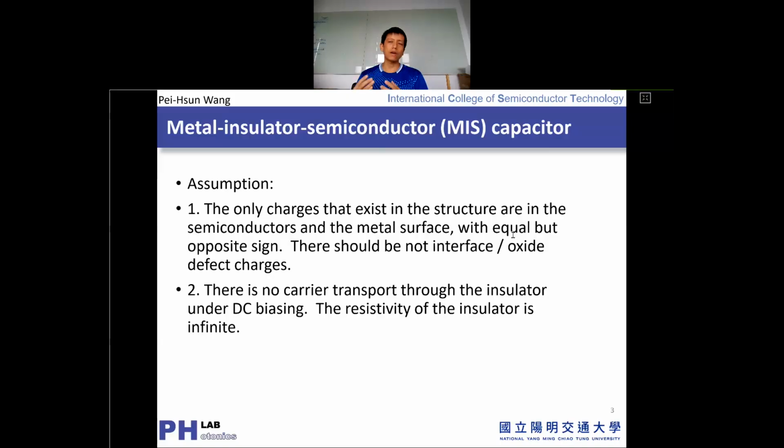So this is easy to identify. We can just have a silicon wafer, and then we do the oxidation. And then we connect both layers with metal connections, either the ohmic contact or the Schottky barrier. Then we can see what the capacitance change is. So it is the most widely used metal insulator semiconductor capacitor. That's what we mentioned, and later on, we combine it with an additional channel and we will realize the transistor with the MIS system.